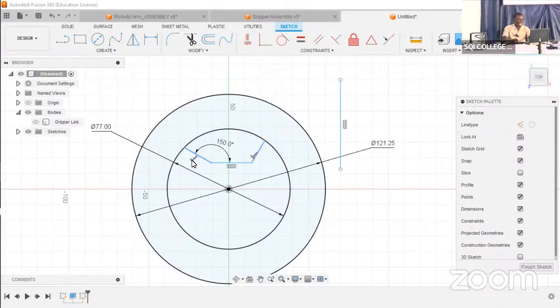So just click on that icon, that perpendicular icon. That perpendicular icon is the one you have here, right? So click on it over here and hit delete on your keyboard. The moment you hit delete, it's going to be done. That means that constraint has been removed, and now we can change the angle to whatsoever we want.